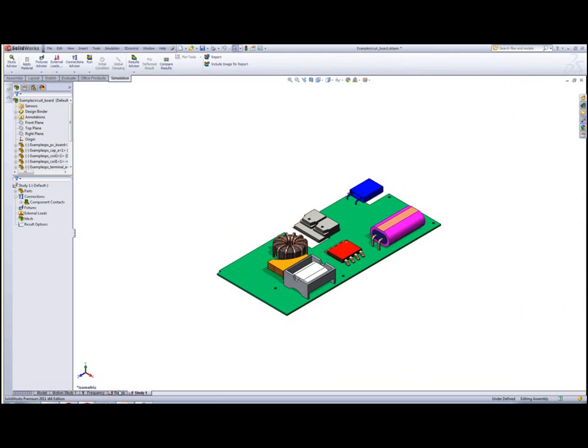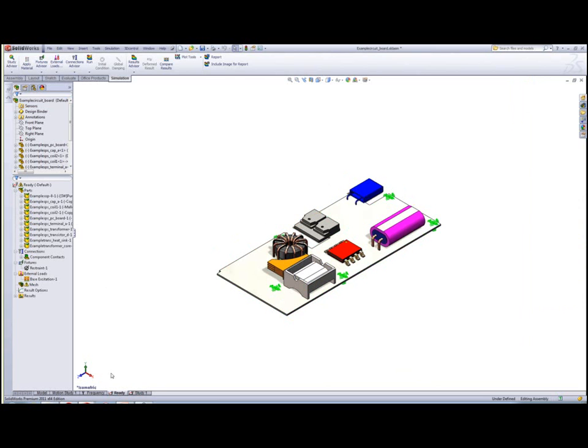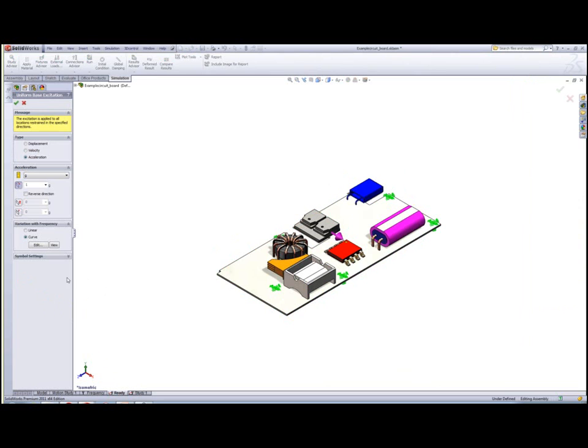I've already done that, and in addition I added a uniform base excitation under my external loads. Let's take a look at that if you'd like. It's a simple one gravitational unit along the plane in an acceleration type of base excitation.